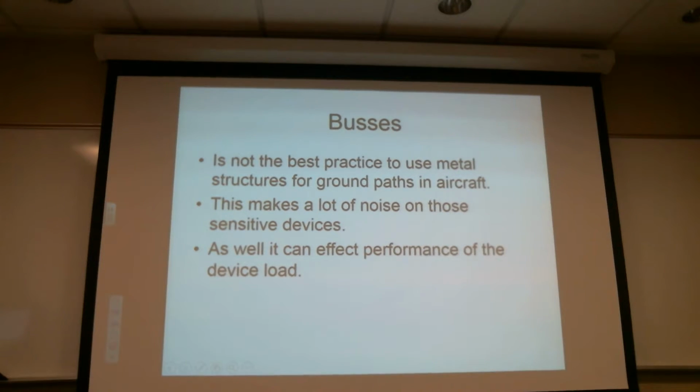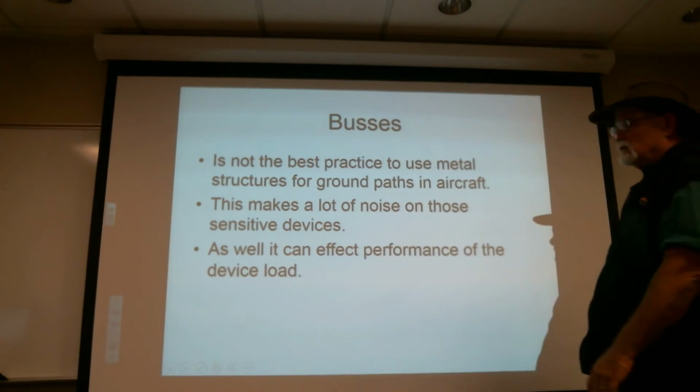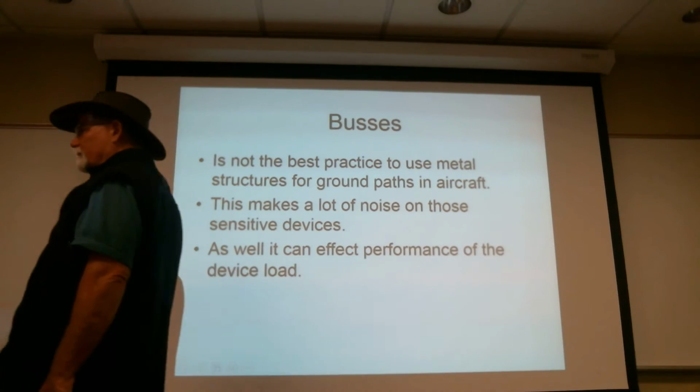And I mean the complete audio circuit. Even the ground for the intercom and the grounds for the radio all had their own common bus. And then coming out of that, the lead from that bus went right down and attached to the bolt that the main ground cable for the battery went to. So it has as straight a shot as possible to the negative side of the battery.